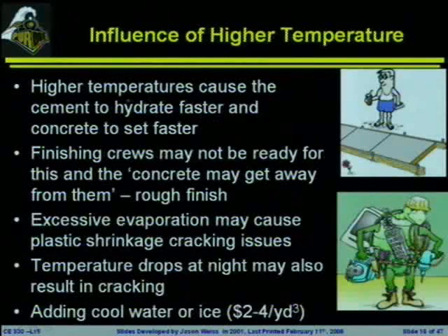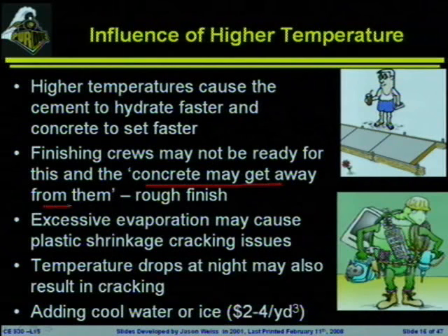So higher temperatures cause the concrete to hydrate faster. This can be a problem because the concrete may get away from the crew. If you hear them talking about it getting away from them, that means that it's set up too quickly. They didn't have time to finish it properly. You can also see excessive evaporation sometimes taking place, where plastic shrinkage cracking can really be an issue.